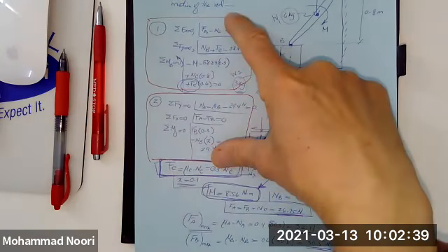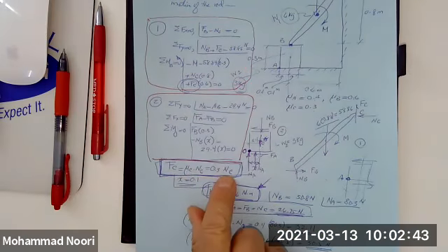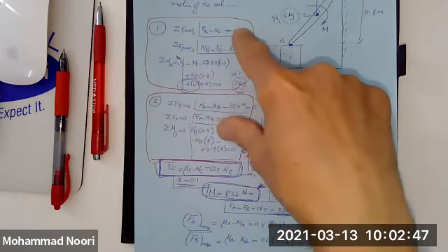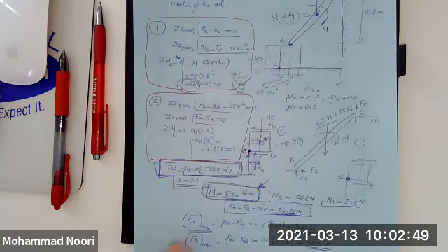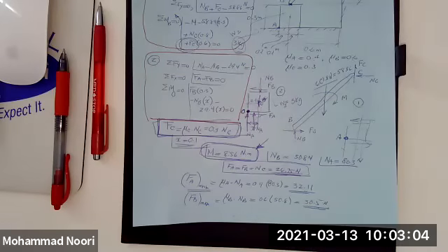We had 6 equations, including FC. Now that we found FC is related to NC, substitute it here, you end up with 5 unknowns, 5 equations, which allows me to find all of them. Okay. That's what I did. Okay. Are we told that C is impending motion? Correct. Yes, it is stated that